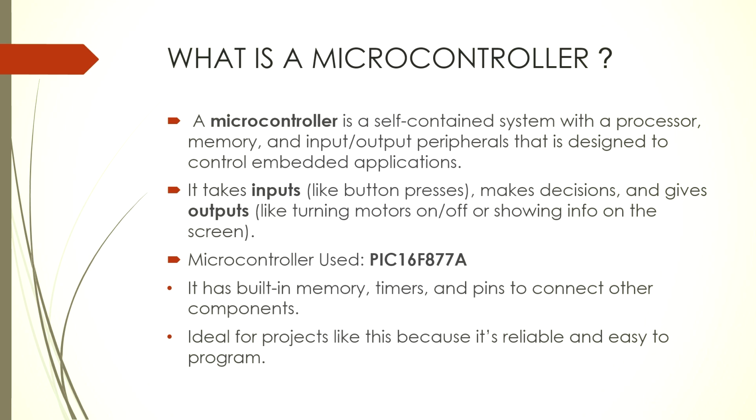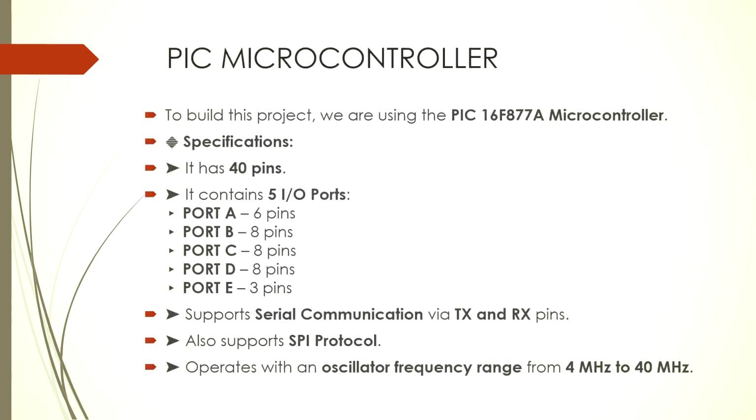PIC16F877A has built-in memory, timers, and pins to connect other components. Having all such properties makes this microcontroller reliable and ideal for this project. PIC microcontroller. To build this project, we are using PIC16F877A microcontroller. The specifications of the microcontroller are 40 pins, then it has 5 I/O ports, then it supports serial communication via TX and RX pins, also supports SPI protocol, operates with an oscillator frequency from 4 MHz to 40 MHz.